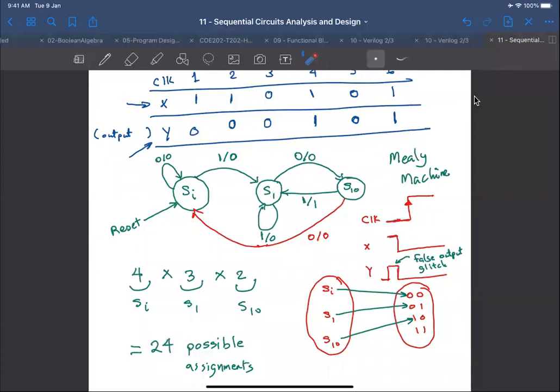No, it's not a hardware problem actually. Because we expect the input to be either 1 or 0 here. We are in here, and we expect the input to be 1 or 0, not both. It does not switch during the same clock cycle. But for some reason, our input glitched. For example, the input is supposed to be a 0, but it has a spike, and then it became a 1 for a short period of time. Then this glitch in the input will affect the output as well. The output will become a 1 because of this glitch.